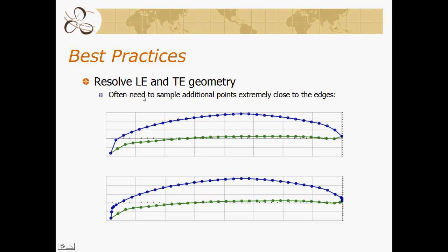Again, if you're just trying to get some basic features out of the propeller, this isn't going to affect much. This doesn't affect the calculation of pitch. It doesn't affect the chord length. It just affects really the nose hydrodynamics of this section. So depending on whether you're truly recreating this propeller or just using it to extract the parameters you need, that may dictate how much time you put into editing the points on the nose. And this is just highlighting those changes here.